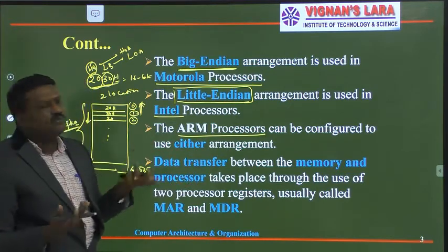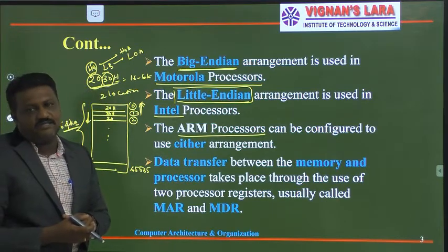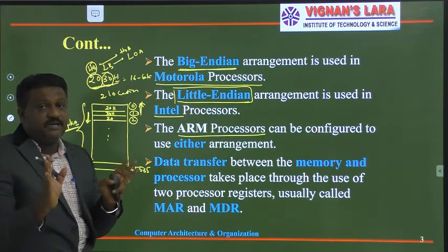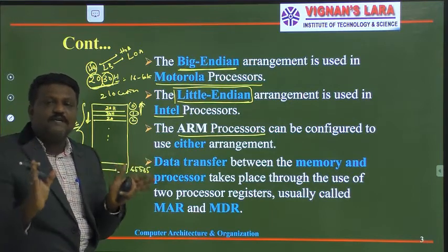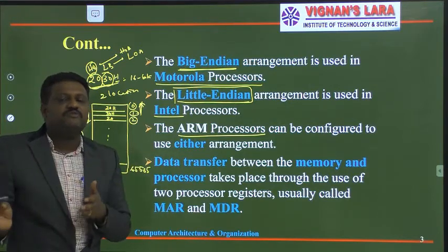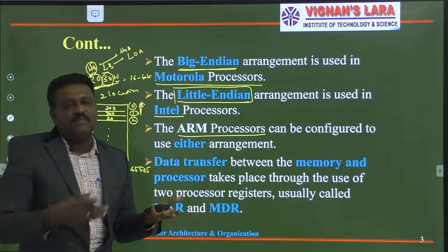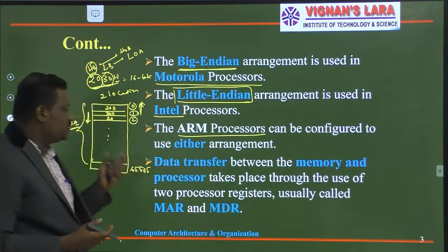That means you can use either the big endian style or the little endian style. But you have to remember that the big endian arrangement we observe purely in Motorola processor based systems, and the little endian arrangement we observe in Intel processor based systems. But coming to ARM, it will support both. That's the meaning of this.